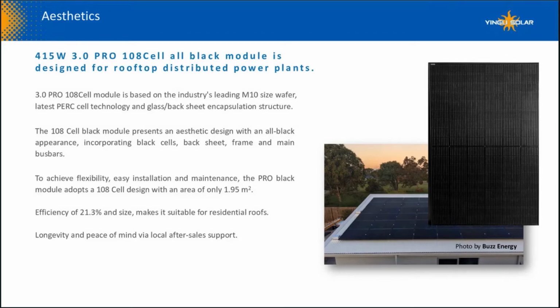This is because the white backsheet material can reflect light back into the silicon structure, thereby boosting power output, whereas the black backsheet itself absorbs light, so its output is slightly less. For some homeowners, the interest in a sleeker looking all-black module may outweigh any small reduction in power class. It's another way of adding value to the look of your home and its potential future selling price. So on one hand, we have a home solar plant that not only saves money and the environment, but for some homeowners, it just looks nice.